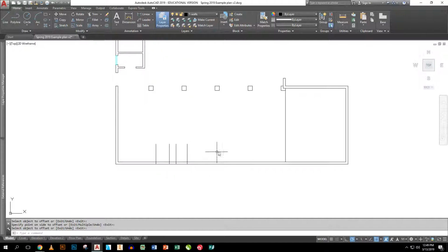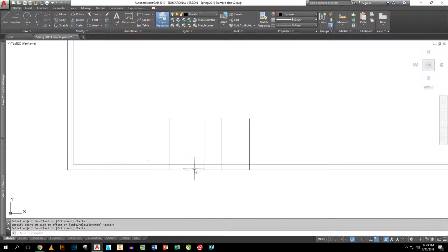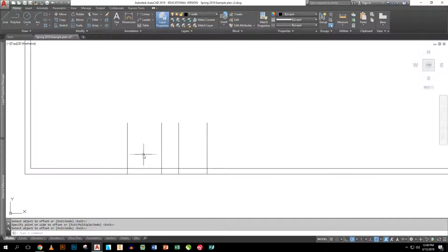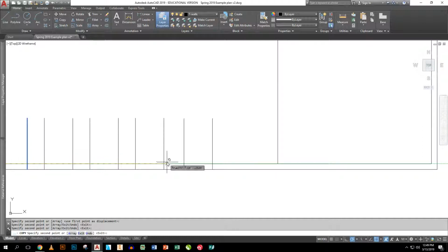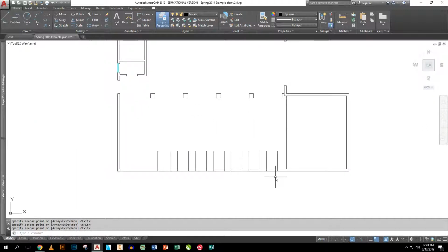Now, I don't really care where they hit right here. This is actually a step down into a sunken area here. I'll put in some transom windows down there. So what I'm going to do is come back over here and space this out. I'm going to simply copy these 2 lines from this point here to that point there, and just repeat that down there. Now I could also do this with an array function if I did the math ahead of time, but basically I'm just going to space it down there. Now that gives me a decent looking gap spacing situation here.